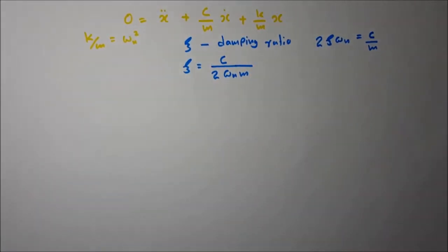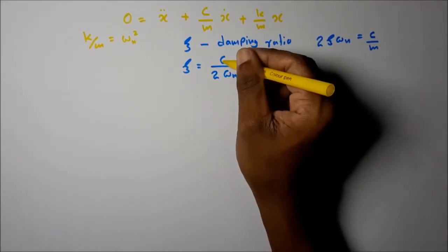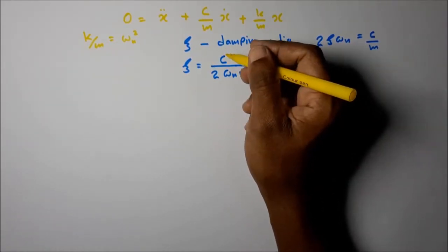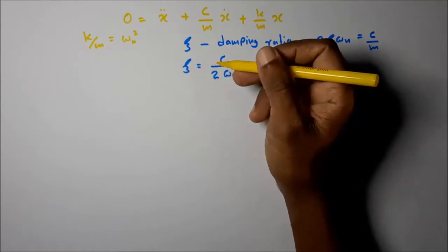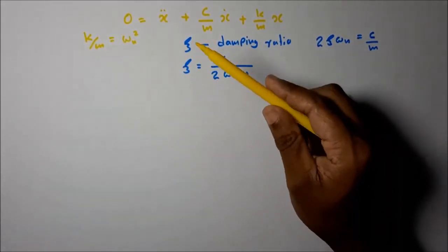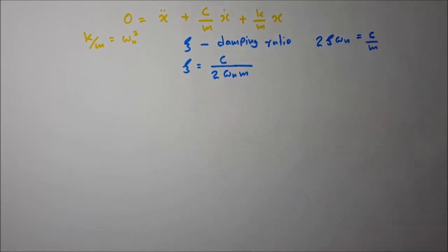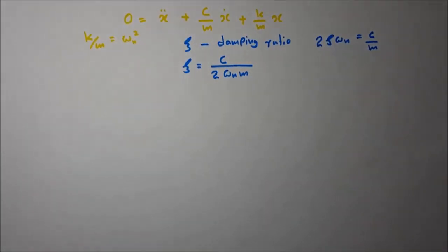The important relationship when solving problems is the relationship between c and theta. If c increases, meaning the dashpot damping coefficient increases, theta also increases, so the damping ratio also increases. Don't confuse these two parameters. The c is called the damping coefficient, the theta is called the damping ratio. Then this newly introduced parameter I am going to put into this differential equation.